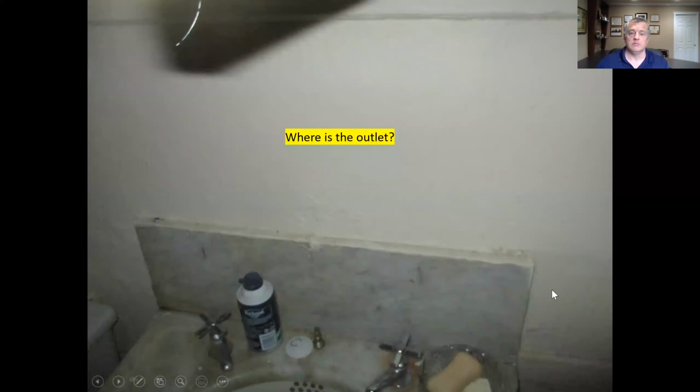How about this one? Where's the outlet? There is none. We still see a lot of bathrooms that have never had a substantial renovation, and there's no outlet in the bathroom. There's a light and a switch, and that's it. Now, you could replace the light with one that has a plug-in, which is really not a good idea in a bathroom. You're not supposed to do that. But you actually have a bathroom without an outlet. So what do we do with the renovation? We'll install one, but it's not even a matter of it's not GFI rated. You literally don't have one. And you see that a lot for a lot of the old buildings if they've never had a renovation.